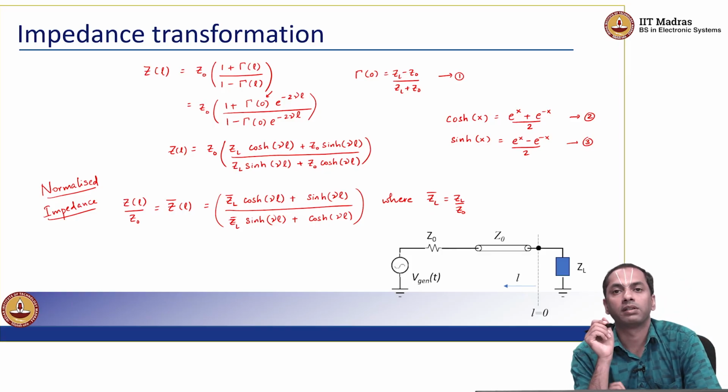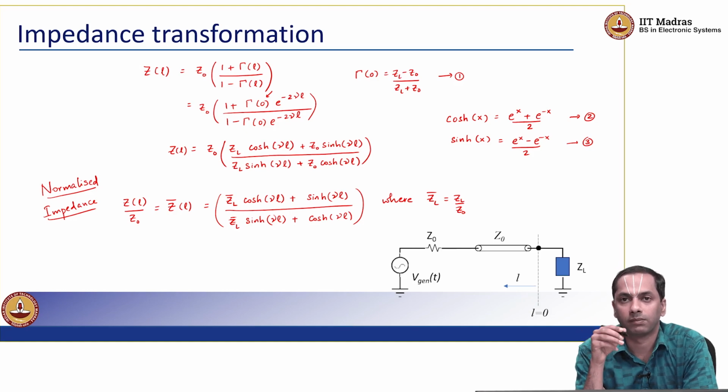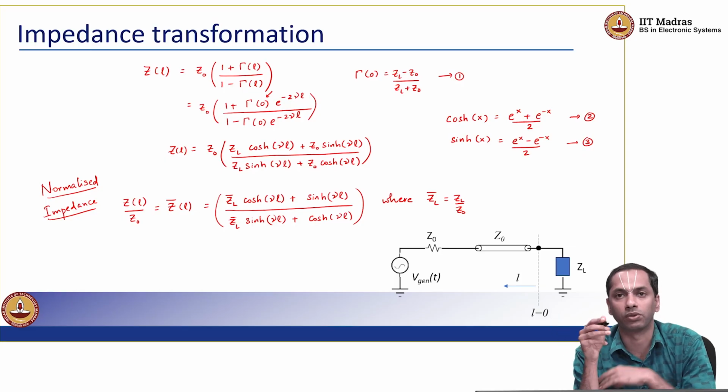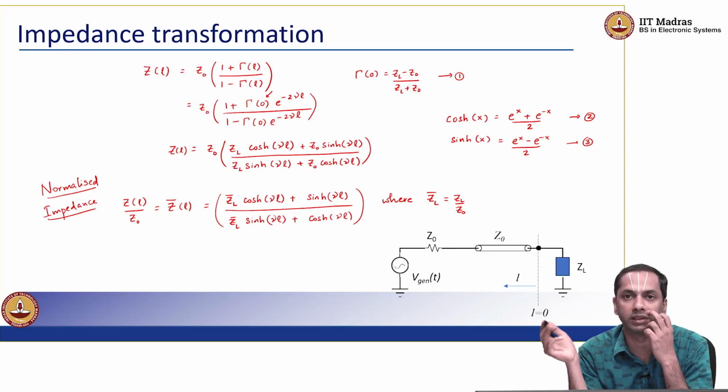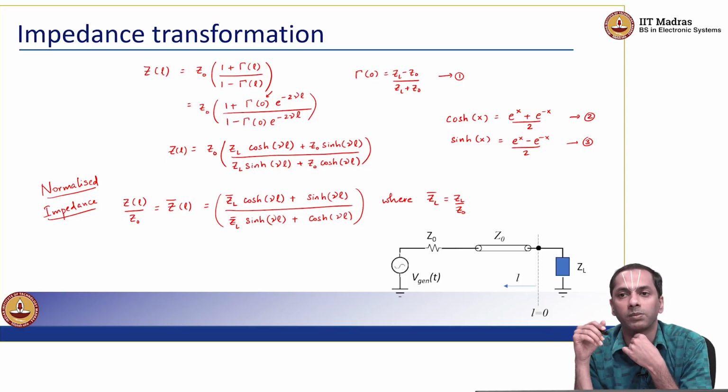Okay, so all this mathematics is essentially trying to portray the fact that the sinusoidal excitations of voltages that are excited at one end of the transmission line propagate in a wave-like form, just as you saw in the case of the beam bendings moving towards the end of the line. You find these sinusoidally varying voltages propagating along the transmission line, reaching the load impedance ZL, getting reflected, say some portion of it is reflected when ZL is not matched to Z0.